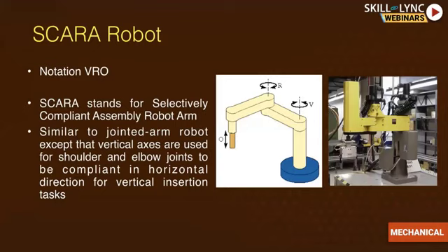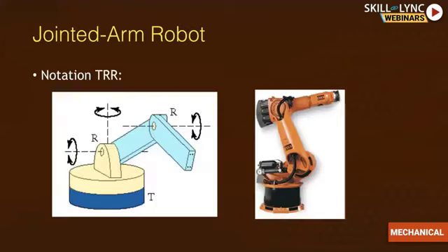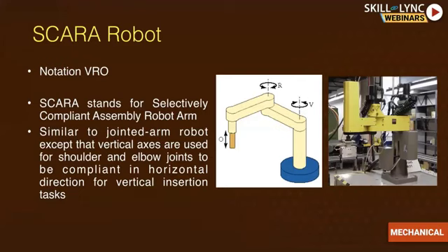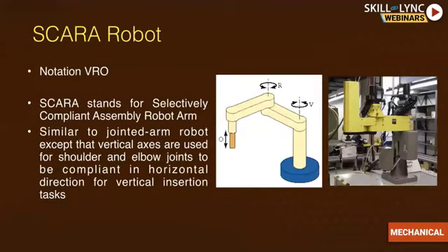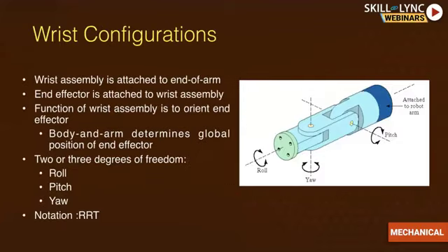That means that joint has a rotation or a translation. Nowadays, some joints have even both, or some are like a screw type, so that's going to have more than 1 degree of freedom at a joint. But in these slides, each joint has just one degree of freedom. So 3 joints, 3 degrees of freedom. And I'm going to attach a wrist to any of these 3, so totally I'm going to have 6 degrees of freedom. So most of the industrial robots we have now are all 6 degrees of freedom.